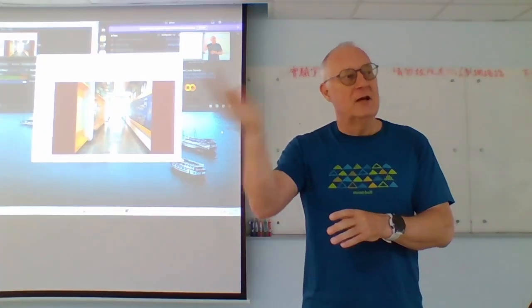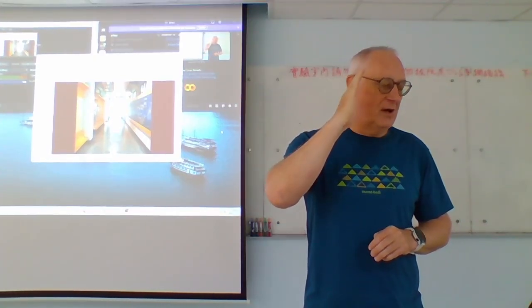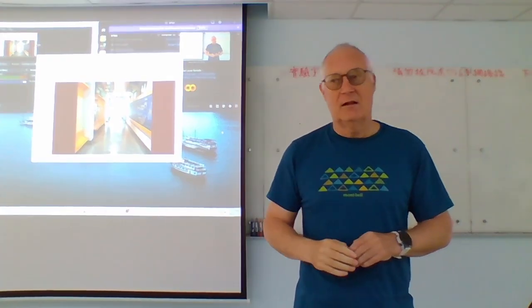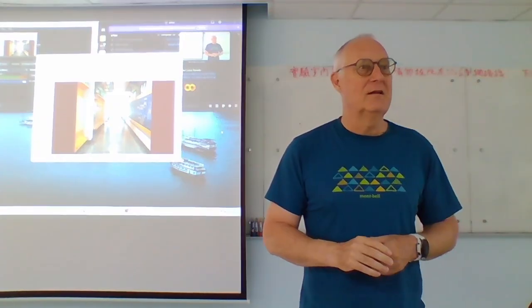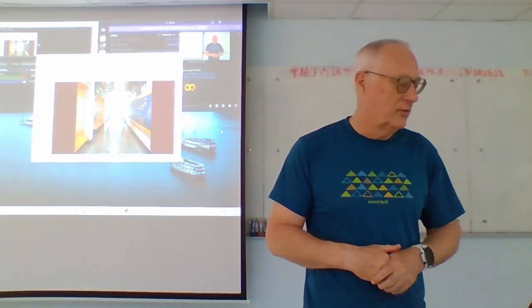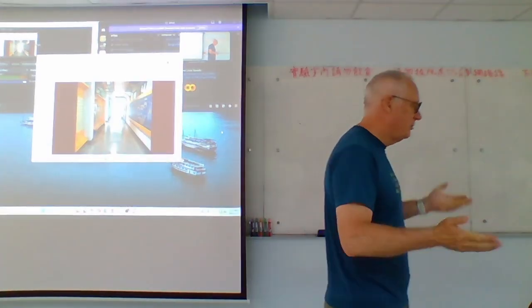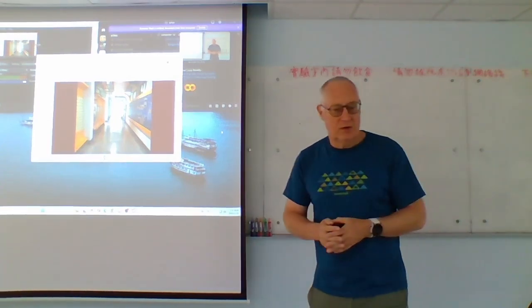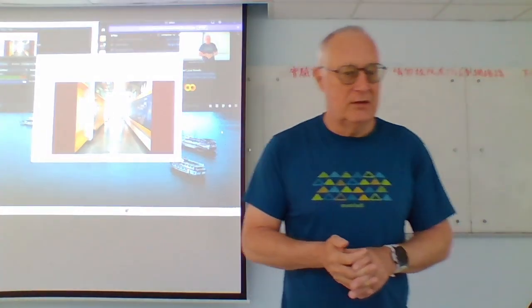So as the robot is rotating quickly, your accelerometer data is not very useful. But if the robot is at a static, stable angle, then your accelerometer data is very useful and very accurate, and you can reset your gyroscope angle. So then you need to fuse those two readings. So that's a possibility. And what we really do is we're implementing Visual SLAM in order to get the velocity